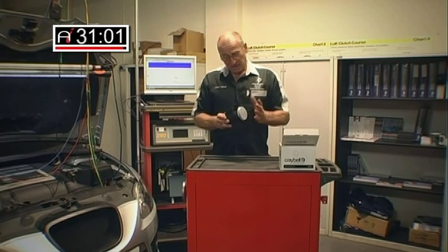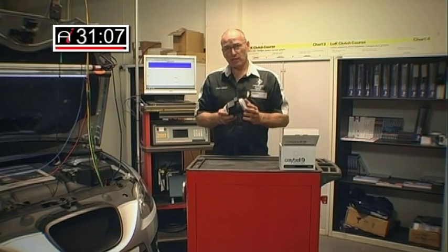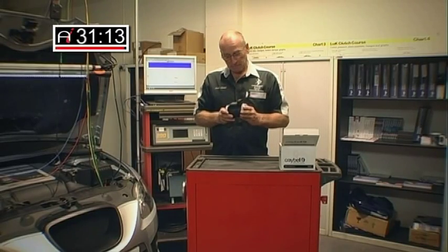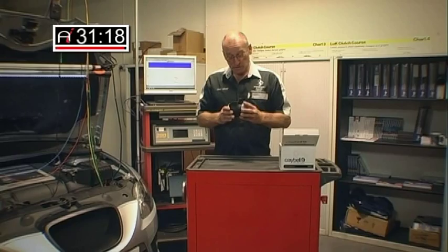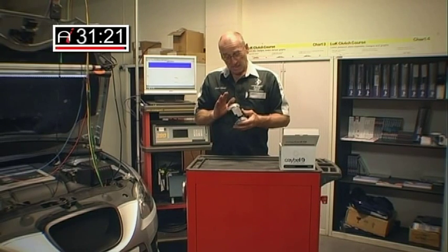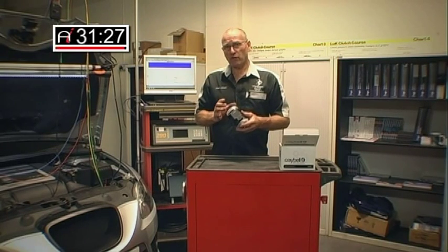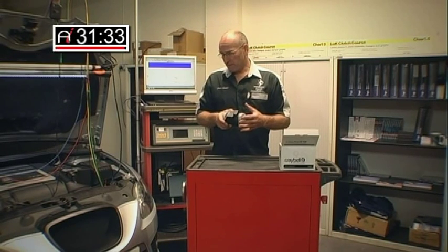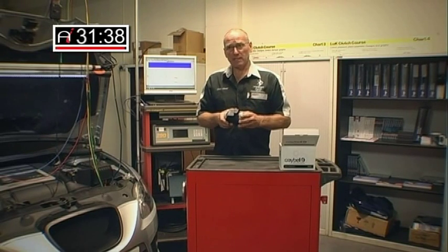So I think that more or less concludes, I hope, some thoughtful suggestions before you blame the air mass meter. Look at other potential conditions. We test integrity of air intake systems using smoke, and we're going to demonstrate that also a little later on. And bear in mind that if they do become damaged or affected, try and think about curing the causes and not dealing with the symptoms. And quite often there are some very, very progressive treatments now for engines, some flushes and intake system treatments, which can help recover the condition, especially with diesel.